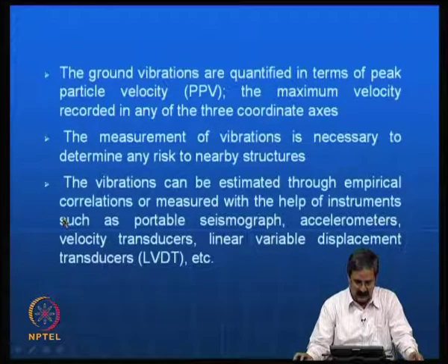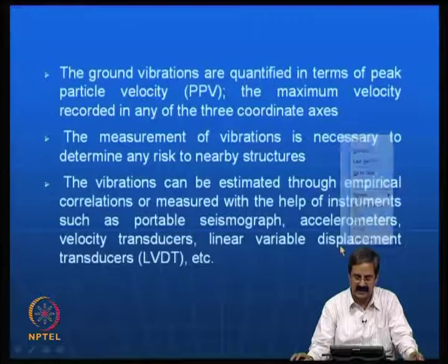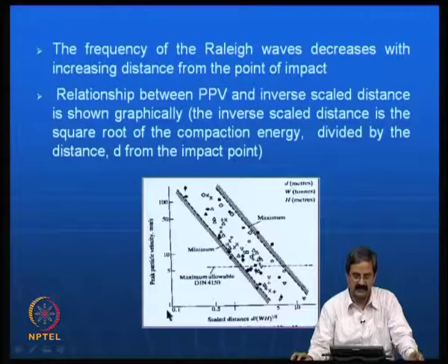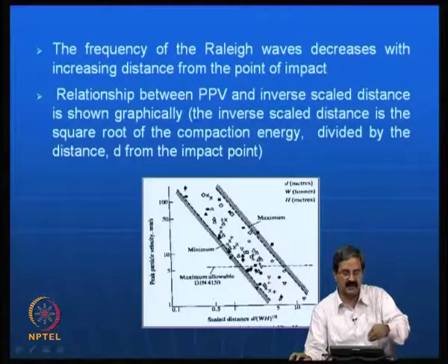So, the vibrations can be estimated through empirical correlations or measured with the help of instruments such as portable seismograph, accelerometers, velocity transducers, linear variable displacement transducers, etc. So, you have a number of equipment like this, and the relation between the peak particle wave velocity and the distance is like this. Say, for example, you have peak particle wave velocity and the distance. So, depending on the distance, one can